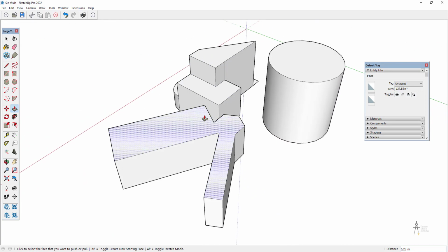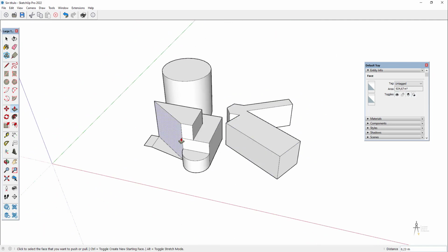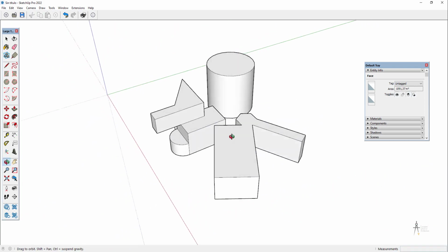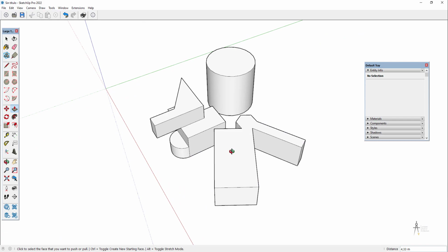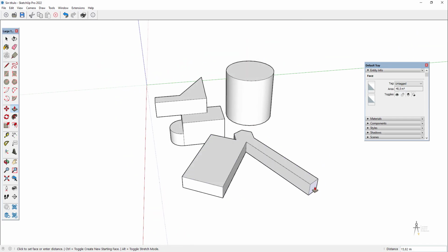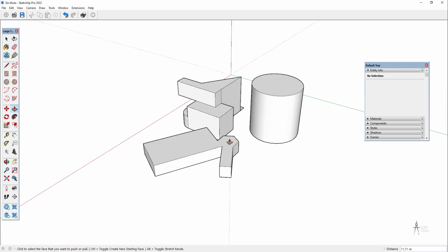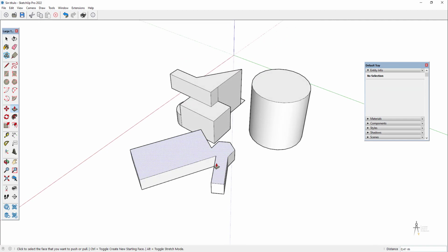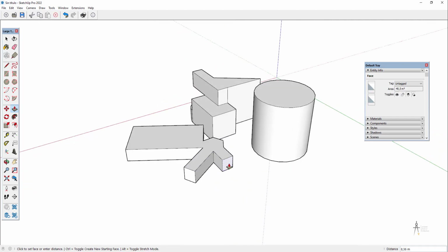So I would love you to play around with this. Maybe draw some two-dimensional shapes and extrude them, and then start to design your own spaces from the new faces that are created automatically. In architecture studios, it's very useful because with just a very basic plan and a couple of volumes, you can come up with ideas just by doing what you can see I'm doing on the screen right now.